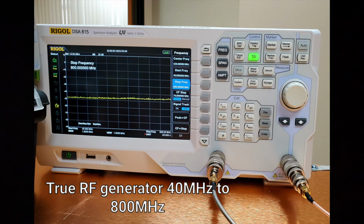This is a picture of the generator that we were using, a true RF generator. You can't bring it up higher than 5 milliwatts, because that energy would be a lot for a lot of equipment, especially anything that's an O-scope or other spectrum analyzer. You can burn out the front end. So what you do is you're showing that you can get it out there, but you're reducing it down in height. You also want to prevent clipping. So it is showing two things. One, you actually do have energy coming out. You are really running from 40 megahertz to 800 megahertz. And that is required by any standard spec.